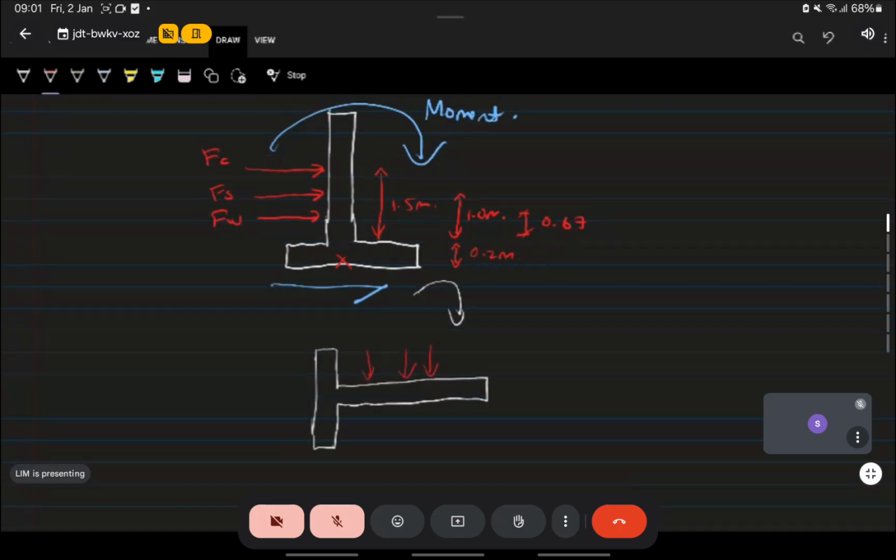So basically, a beam and column. Correct, a beam with column. Your base now becomes a column. Your stem is actually a vertical cantilever beam. It's actually a beam cantilevering from a column. So now to calculate the moment, you assume the whole thing's cantilevering.